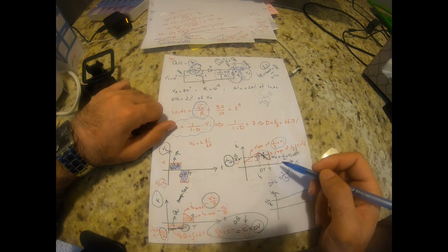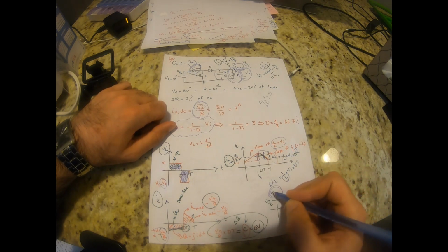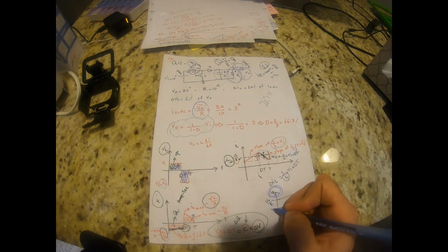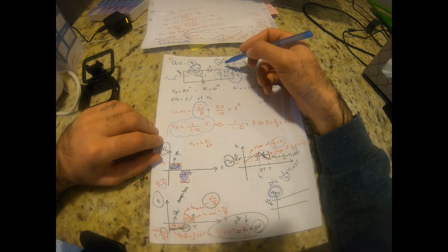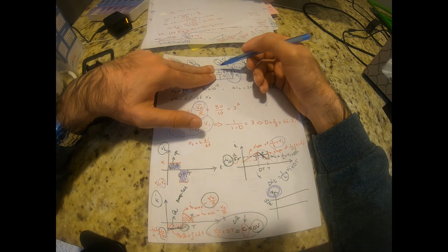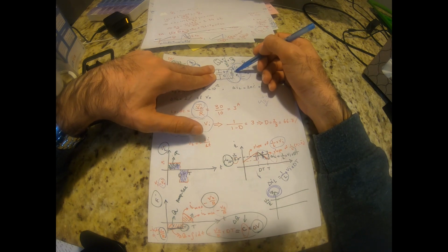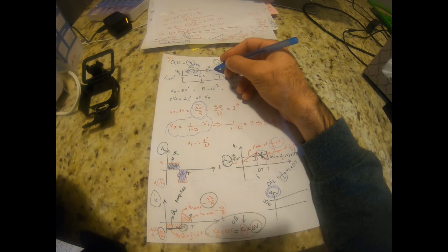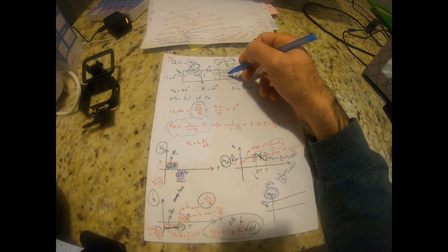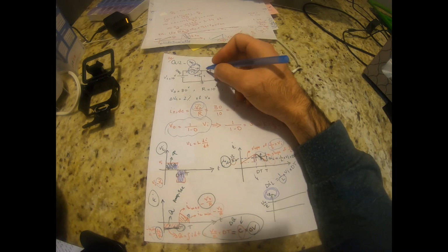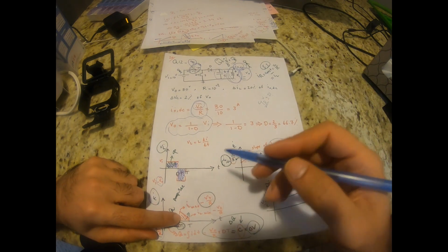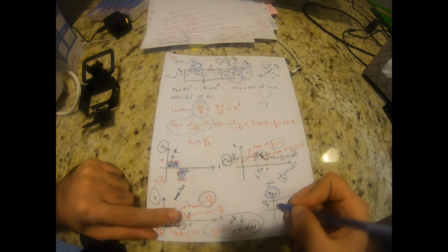So these two I already explained. We also said that the resistor current, we assume that it's always constant, equal to V over R. When this diode is not conducting, IC is going to be equal to negative IR. When the diode conducts, based on KCL, IC is going to be IL minus IR, right? So it's going to have the same shape as IL, but it's shifted down this much.